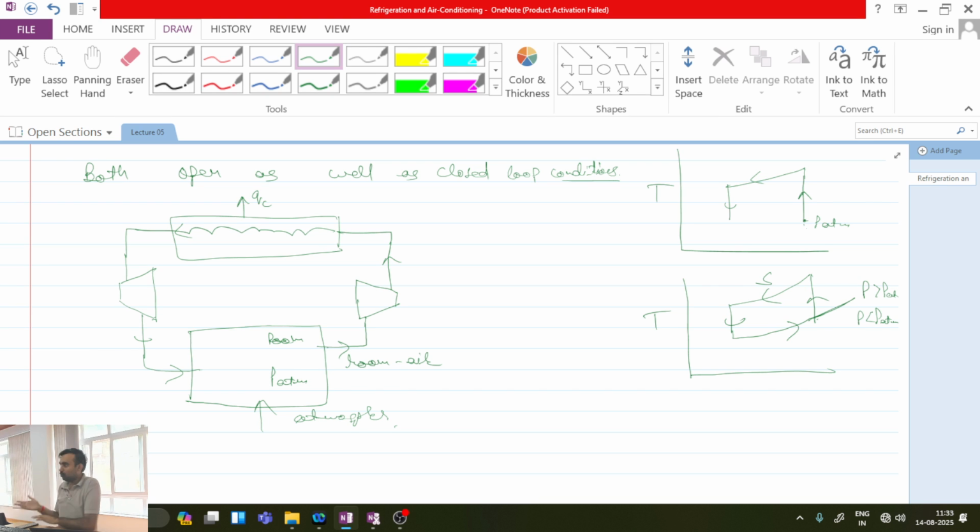So this is one way of operating an open air refrigeration cycle, particularly when the low pressure heat exchanger is removed. Is this point clear? So when the low pressure heat exchanger is removed, the deviation of this cycle from the actual cycle is very less. There is not much deviation.